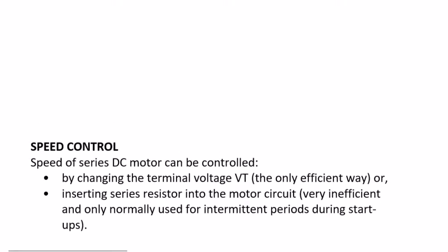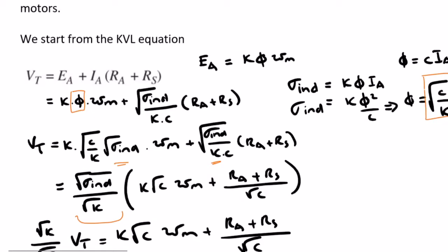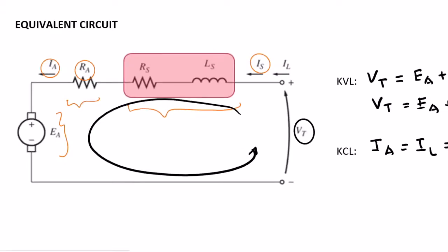because if you go back to the equivalent circuit of this motor, if we add a resistor in series here, to enable us to change the magnetic field, the current that goes through this resistor can be very high, because now it's not only the field current but also the armature current that will flow through this additional resistor.